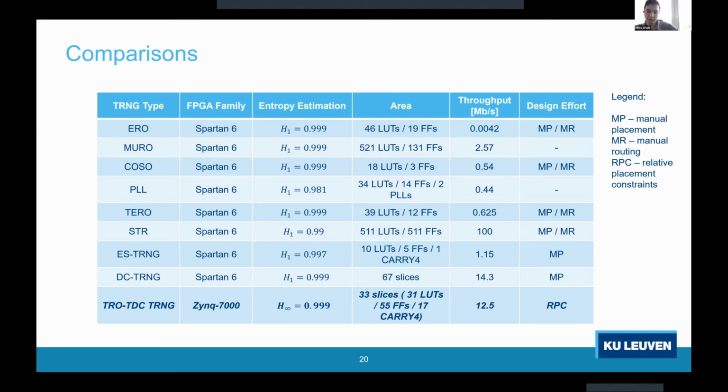What we saw recently, by Lawrence Walker Chess last year, is that it turns out that reseeding of PRNGs might be needed much sooner than we expected. And if you have one PRNG for your masks, one PRNG for your keys, and so on, the number of TRNG bits that you need to reseed all these PRNGs grows very, very fast.